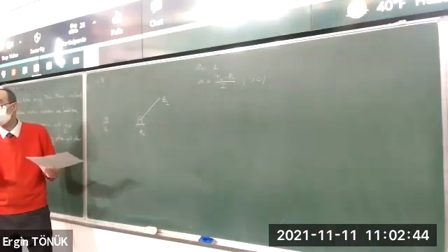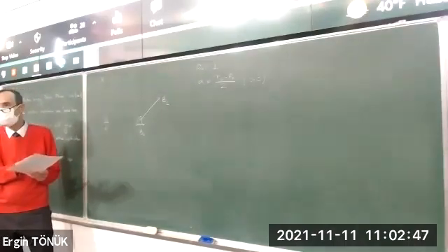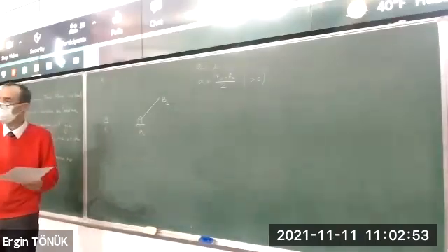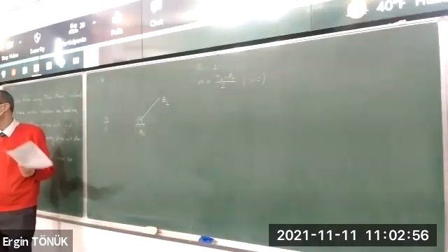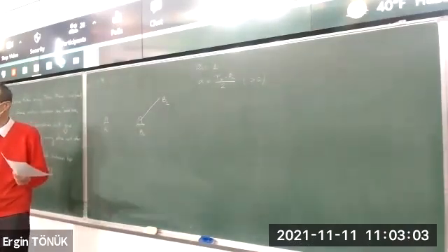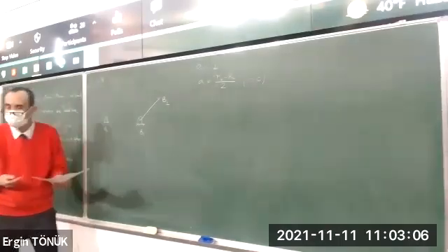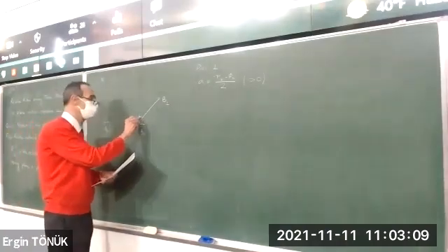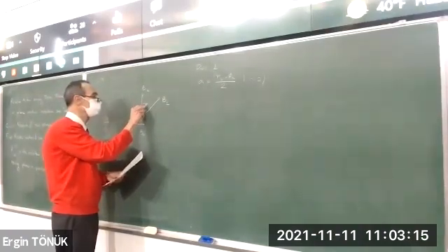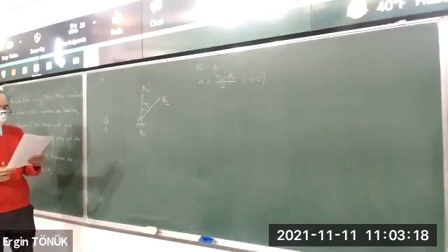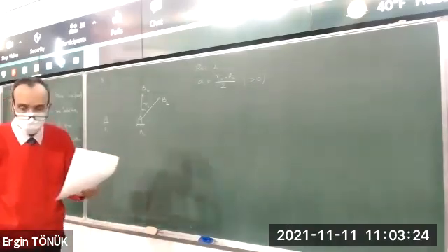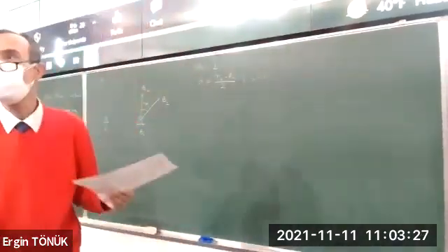So that's another design method. In the previous one, all the link lengths or link length ratios, A2 to A1, A3 to A1, and A4 to A1 were found from the procedure. But here, you select one of the link lengths, or if you like, the A4 to A1 ratio. Okay? So you can obtain B2 by rotating this side by psi 1, 2. Then you can draw the perpendicular bisector B1, 2. So that's another procedure.